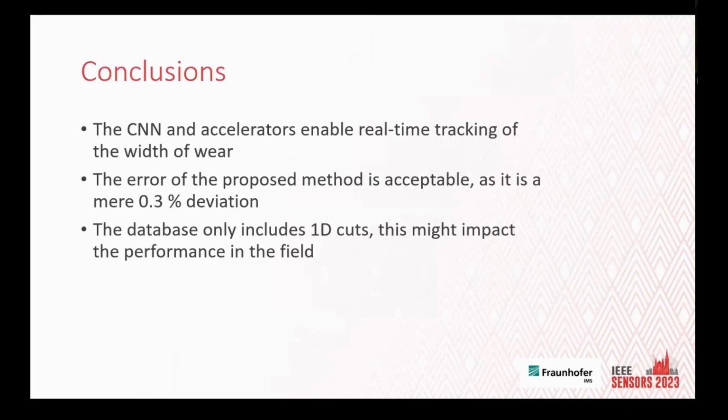Unfortunately, there's also a couple of drawbacks when you look at this research project, which worked quite nice. But if you want to deploy it in the field, as I mentioned in my introduction, we've just used one-dimensional cuts of the steel rod. And there, the method works quite well. But if we imagine our CNC machine working on real products, the movements get much more complex. And it might be that it's much more difficult to determine this width of wear from the acceleration data, from the vibration. Hence, we want to investigate the performance in the field as well with our project partners and see if we can confirm our results or whether we have to change something about it.